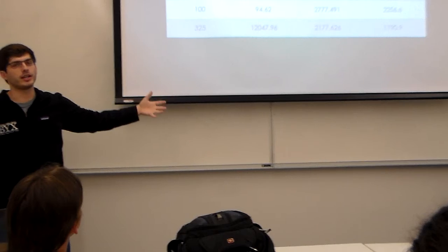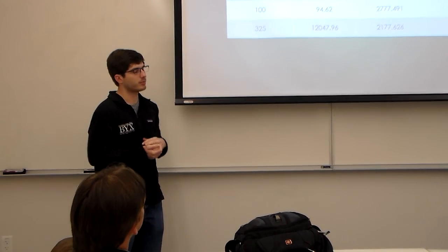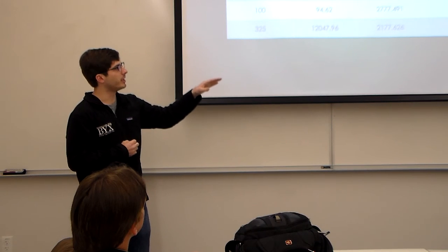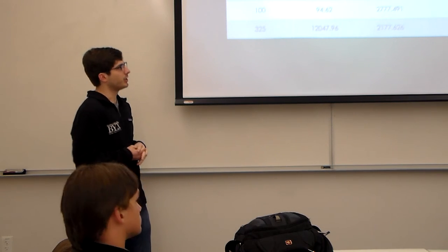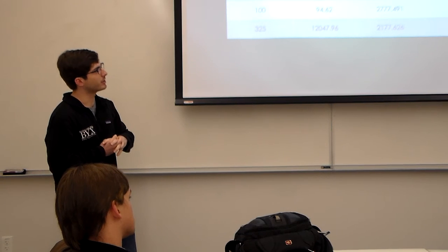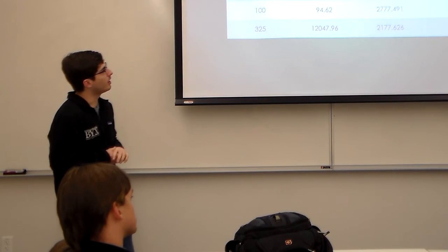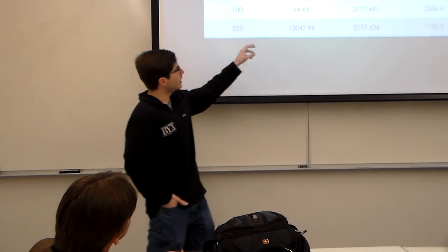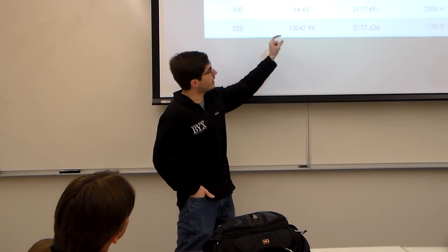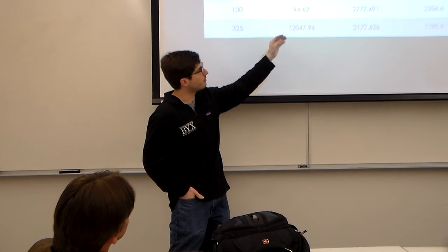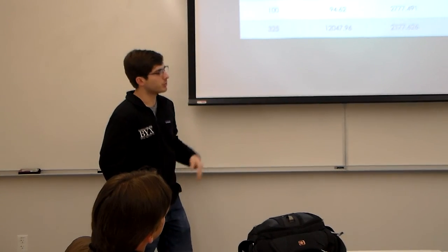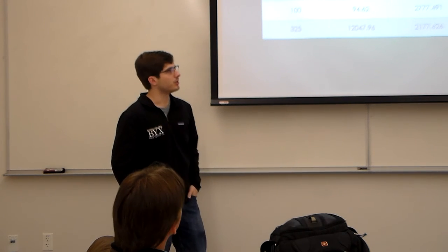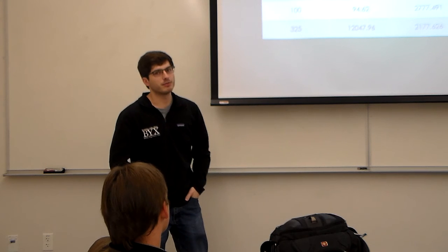That's definitely not right. This is probably due to the curve fit: the slope of the PVT is so small at the beginning compared to the rest that Excel doesn't really know what to do when doing a best curve fit. But we can see that as we increase the temperature, the pressure becomes more accurate to what it is in the steam tables, and our calculated enthalpies start to follow the actual trend that they're supposed to, where they decrease as temperature goes up. But they're still off, and my guess is that this is due to the best curve fit of Excel.